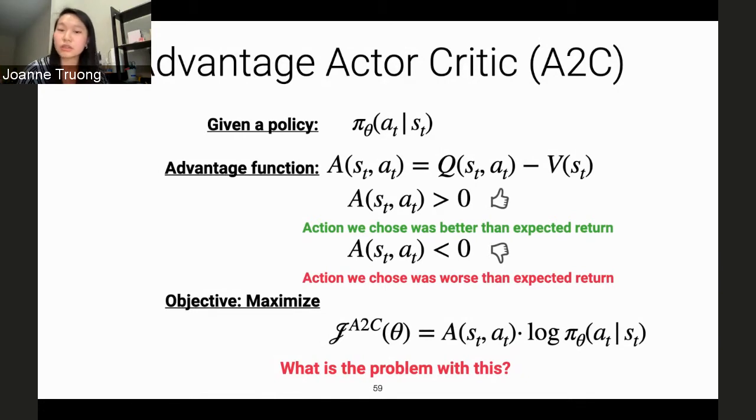There is also follow-up work where we remove this reliance on a perfect GPS and compass sensor, and that's work done by others in my lab. You can either use visual odometry or other methods to estimate this and learn how to track yourself along the way as you're training your policy. And there are other ways to combat this.